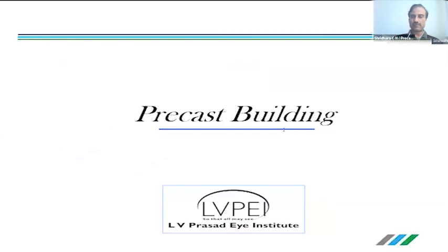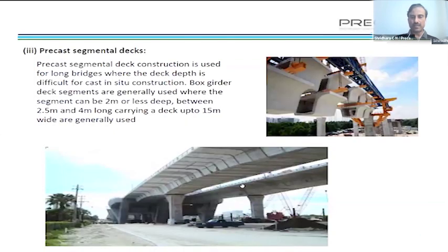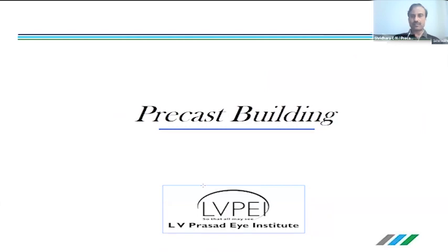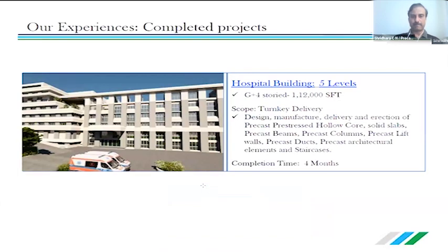And some people will do precast pre-stressed girders, and they will do slabs as cast in situ also. That all depends on design. This technology in bridges, especially, has been used for so many bridges in India also. Anywhere you go in any major city, you'll see the flyovers and metro are done in precast only.